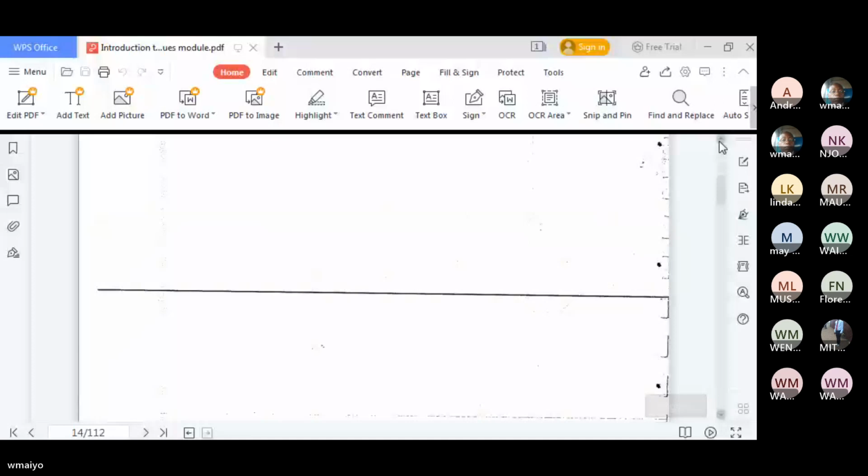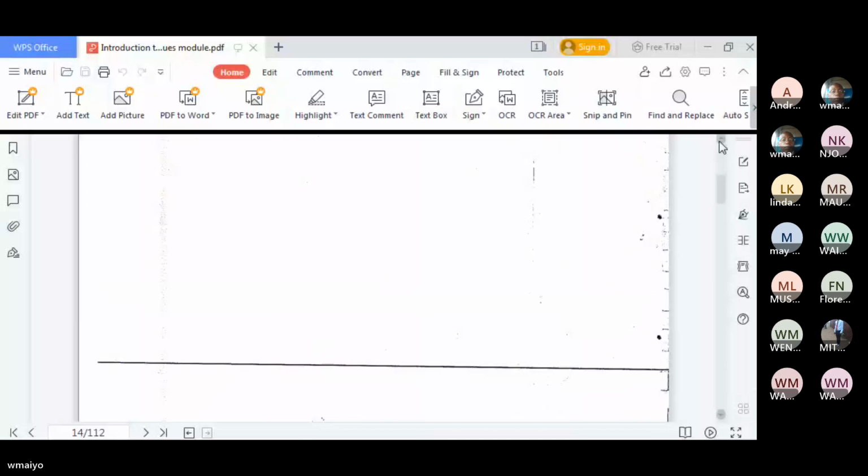So they are unidirectional. You can have the results increasing slightly or decreasing slightly consistently. So you have results that are actually below the average or below the expected, the true value. Their causes could vary from the analyst, from wrong calibration, faulty instruments, and so on. These are things that, once you are able to identify, you can minimize. So they are referred to as systematic errors.